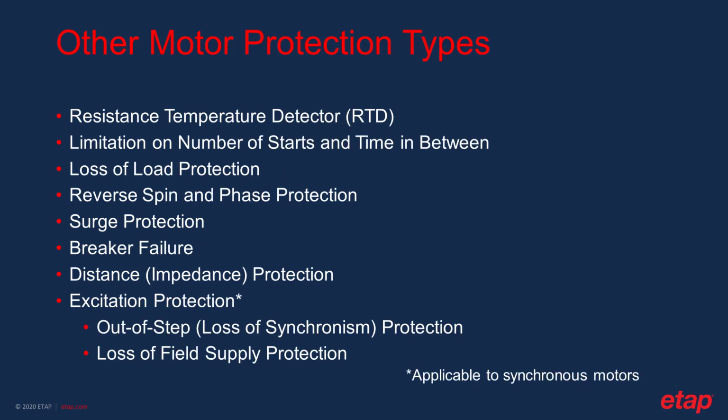You can also have RTD, resistance temperature detector, limitation on number of starts and time in between, loss of load protection, reverse spin, surge protection, breaker failure, distance protection, and so forth for motors. This is just for your information, that naturally in the short period of time we have for this webinar, we won't be able to cover them all.